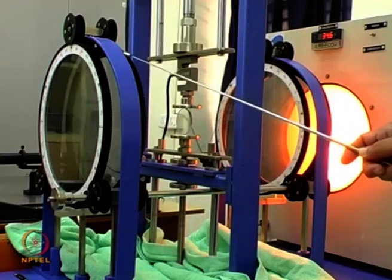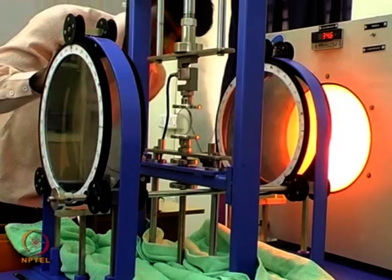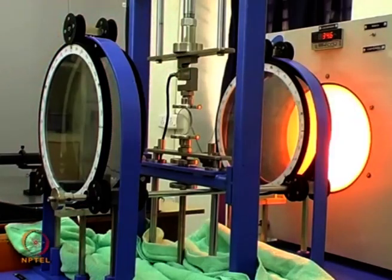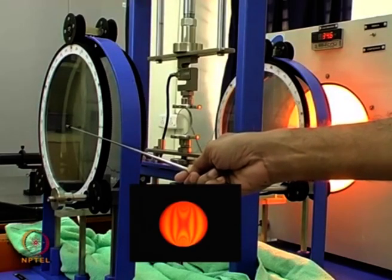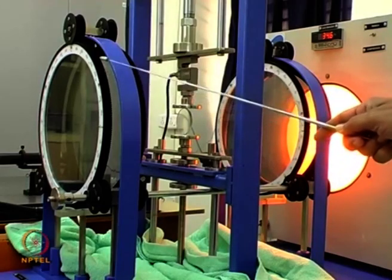Now, what we will do is we will go back and keep the quarter wave plates also in parallel position. They were originally crossed. Now, we will keep it parallel, rotate the quarter wave plate too. So, when I have both the quarter wave plates parallel as well as polarizer and analyzer are parallel, I essentially get a dark field fringe pattern. Suppose I keep the polarizer analyzer crossed, I will have a bright field fringe pattern.